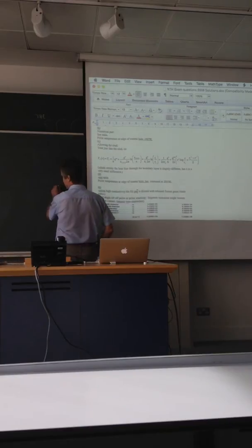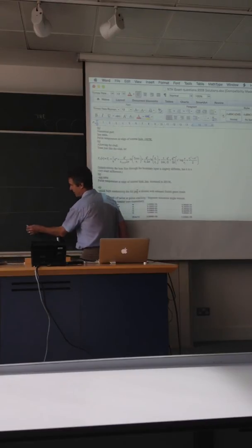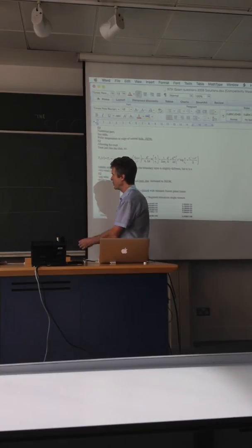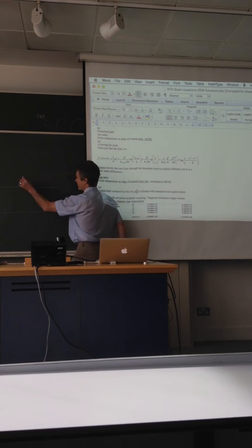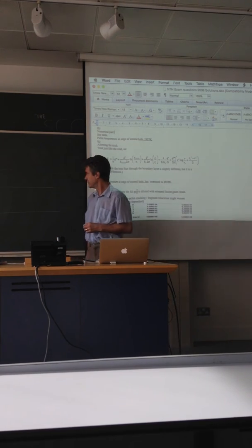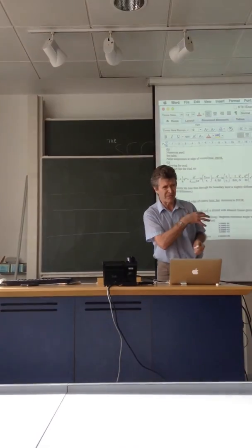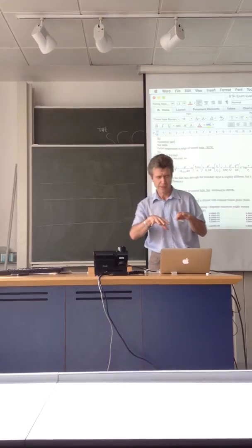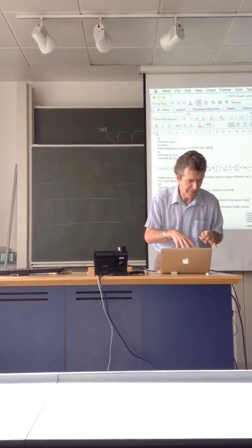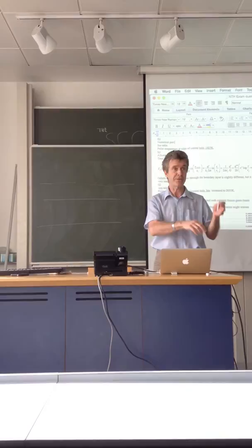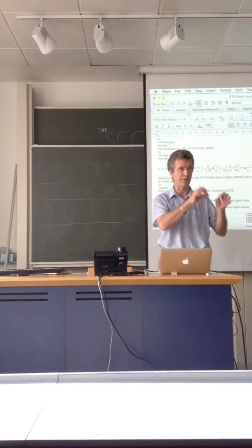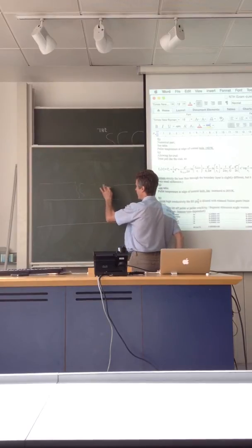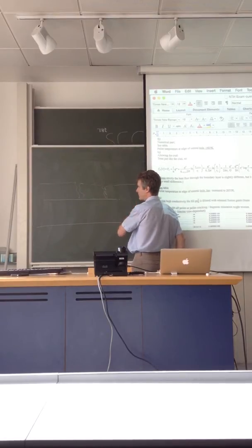What you observe: here's the cladding, and here are the fuel pellets down here. The cladding is of order 0.5 or 1 millimetre, and you get a layer of crud formed on the top, sort of messy, looks like kettle scale. Looking at the top of it, you see little holes like pock marks, a bit like when you cook porridge and it sits steaming on the stove and little steam holes come up, popping. What they are is little chimneys. They go all the way down through the crud, down to the metal.